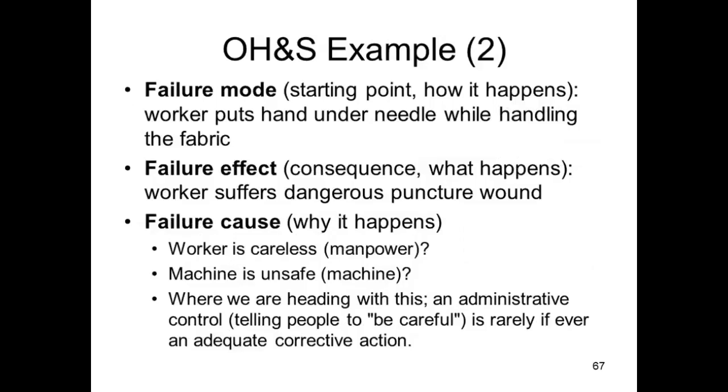Failure mode, starting point, how it happens: worker puts hand under needle while handling the fabric, and according to the reference, this happens 3 or 4 times a day. Obviously, telling people to be careful is not an effective control. And remember, any kind of puncture wound back then was a lot more dangerous than it is today because they didn't have antibiotics, and the tetanus vaccine had yet to be invented.